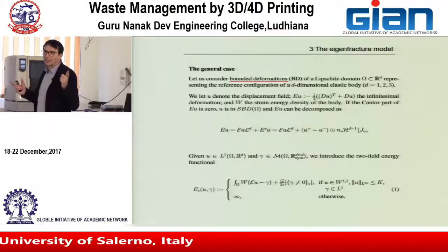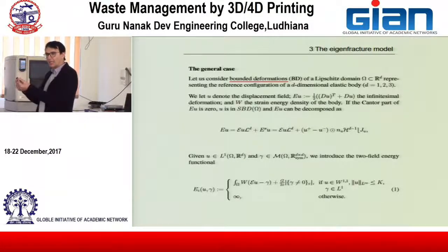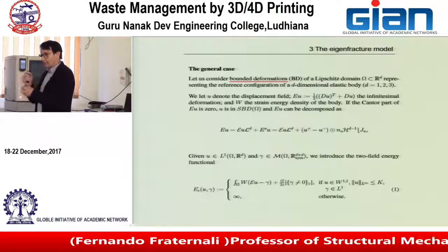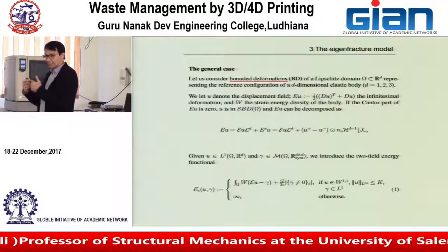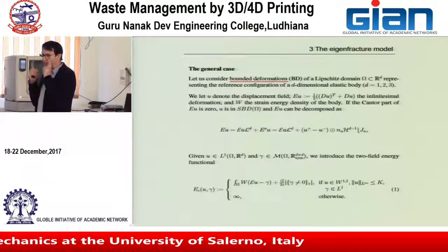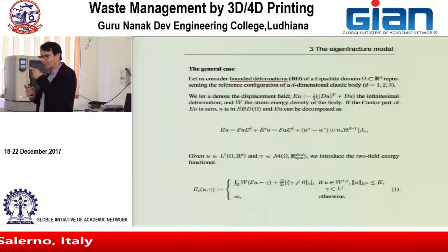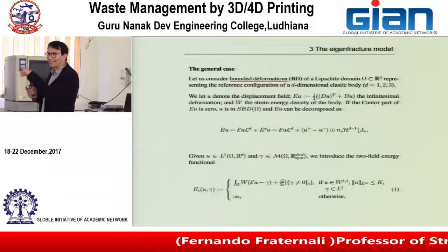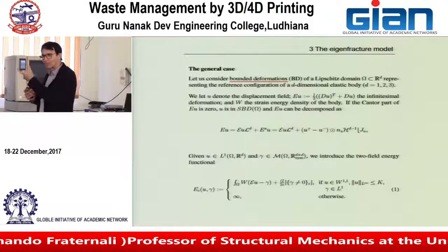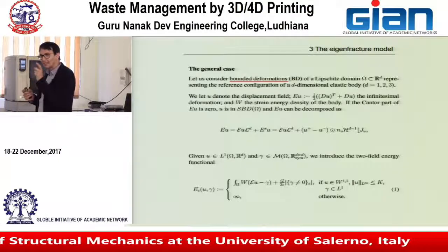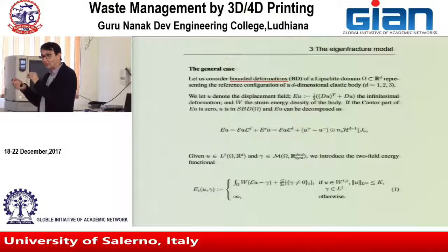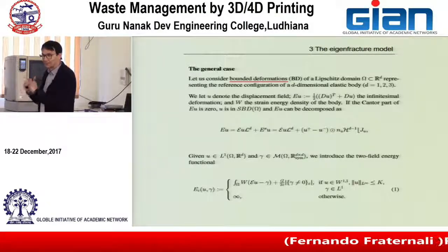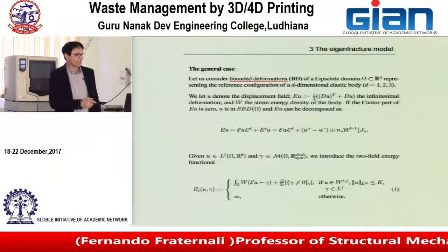Okay? One can think, okay, I take the volume of the element that I want to kill, and I multiply it by some constant, and that's the volume that I need, that's the energy that I need to spend. First, remember that the energy to create a crack is energy per unit surface, while we are killing a volume. We have to normalize the volume to a length in order to obtain a surface. So this is the role of this epsilon.